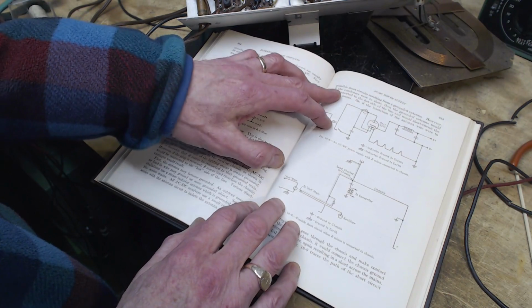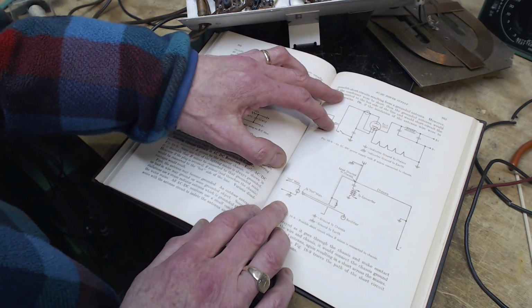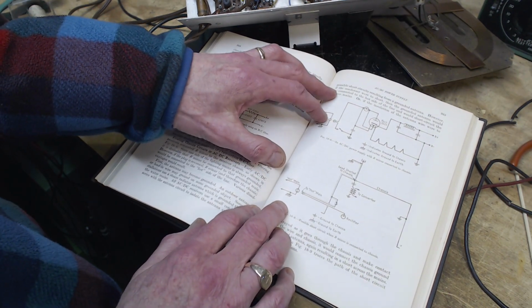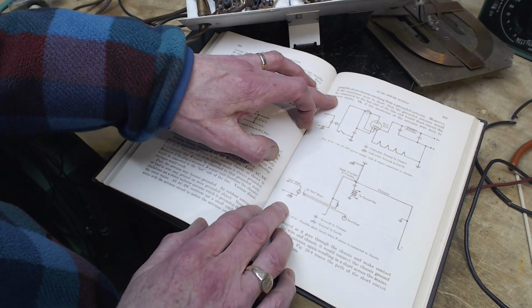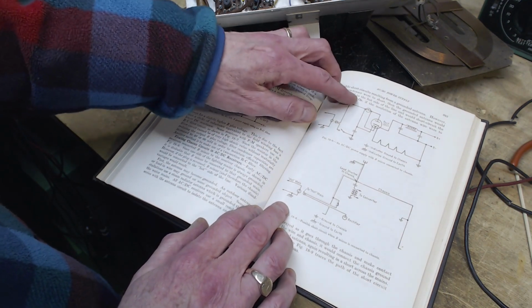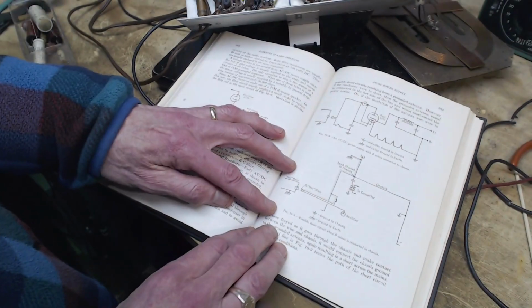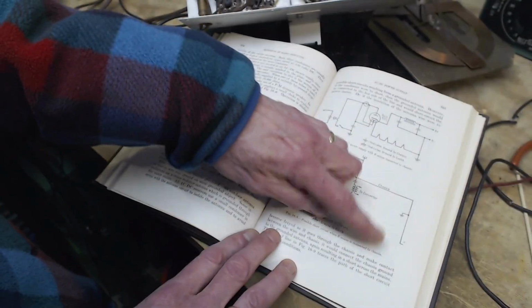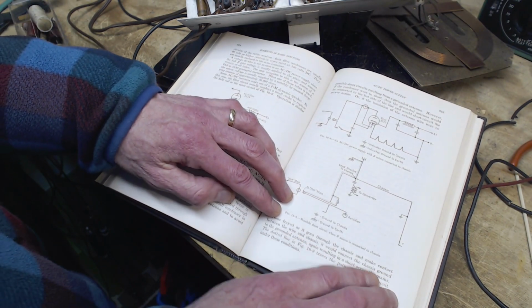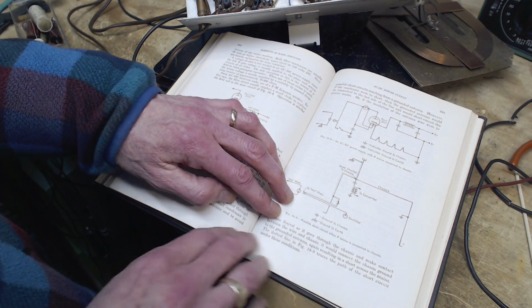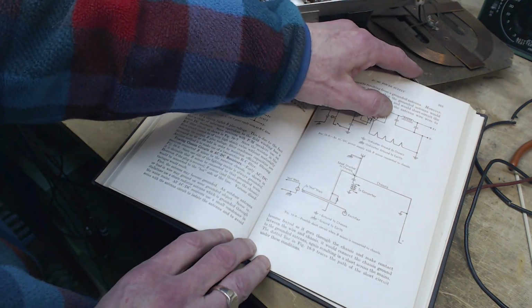However, if the capacitor were to short, then the grounded antenna would be connected to the hot side of the line and it would short circuit the power mains. Or, if the insulation of the antenna wire were to become frayed as it goes through the chassis and make contact between the wire and the chassis, it would connect the chassis ground to the grounded antenna, again resulting in a short right across the mains.